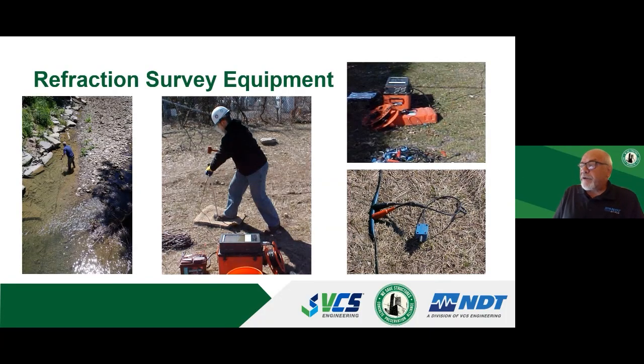On the left is some hydrophones in the water. I think this was a scour vulnerability application for bridges. If we can determine the bedrock is shallow, then we can make an assumption that the abutment or pier is completely founded on shallow bedrock, and the scour vulnerability changes considerably. The middle is the size gun that's kind of stuck through our blasting mat, about ready to release the safety and hit the firing pin with a hammer.